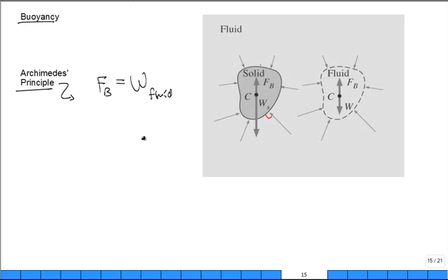And everywhere along there's always a perpendicular, inward-directed pressure force acting on it. True? Conceptually, find that surface area and trace out the same exact area of the solid volume, but don't put the solid there. Conceptually, just have a fluid there. And ask yourself, if the fluid inside this enclosing surface is at rest, well, it is at rest, right? The fluid's not accelerating up or down or to the side or spinning in any way, shape, or form, right? And the fluid that's outside, that's exerting the normal pressure forces, doesn't know if it's exerting a pressure force on adjacent fluid or adjacent solid surface. True?